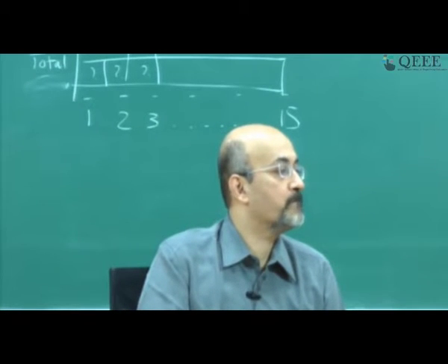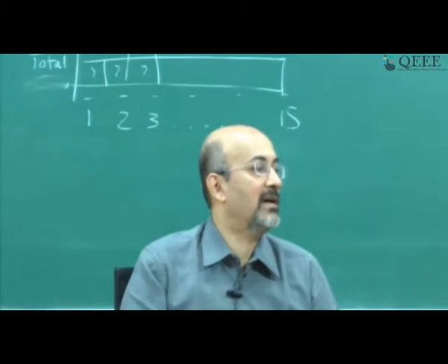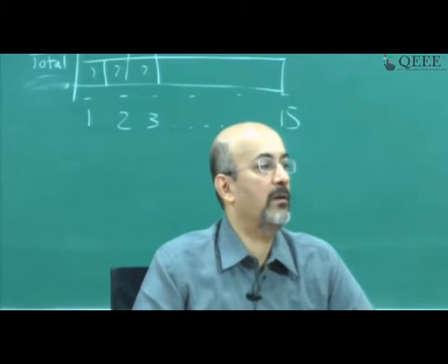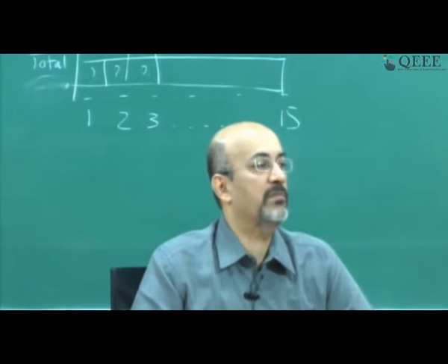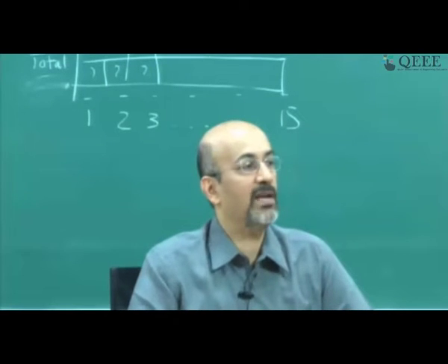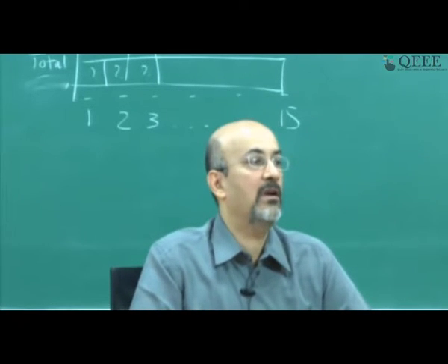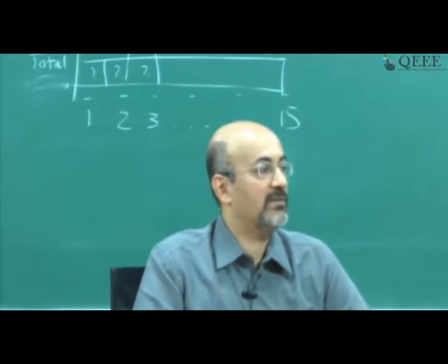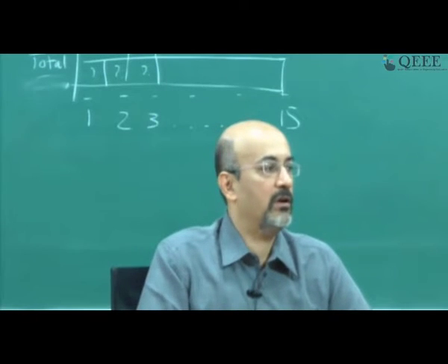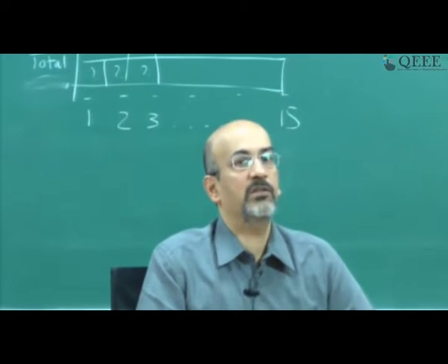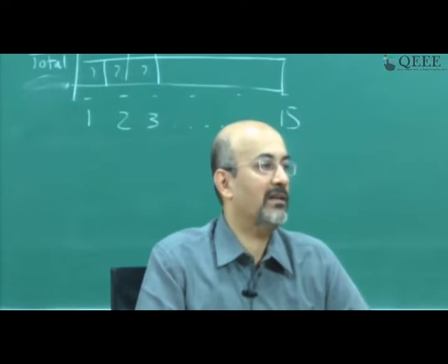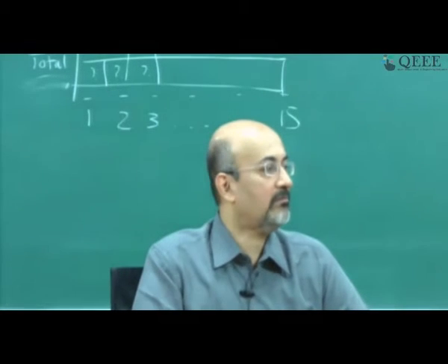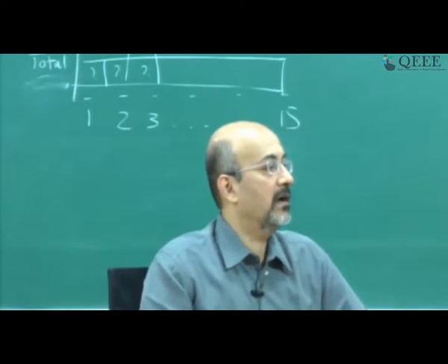Okay, so coming back to this question of whether late start will control cash flow, I'm not saying we should do late start. I'm saying you should find an appropriate, acceptable solution between your early start and late start. If the only acceptable solution happens to be late start, fair enough, but then you have to watch out that those activities will also become critical, and if those activities become critical, your coordination has to be even better. You have to be aware of that. But the critical path method schedule gives you a methodology to be aware of that. Okay, so I hope I've answered the question.